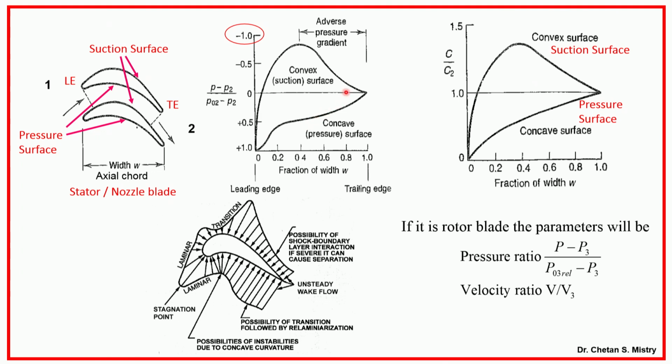Okay. Now, this represents my velocity. The flow over this turbine aerofoil is complex. For the compressor also it was complex, but here, I will have laminar flow near my leading edge, and then, as the flow accelerates, transition will happen somewhere here, and after transition I will have turbulent flow.